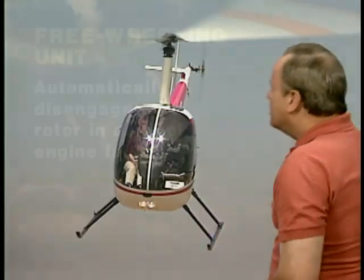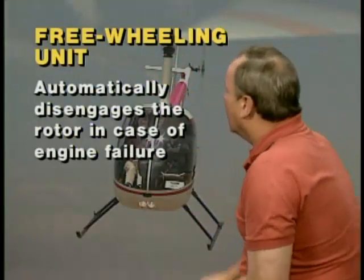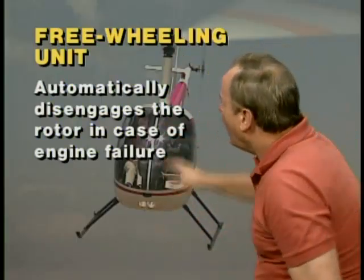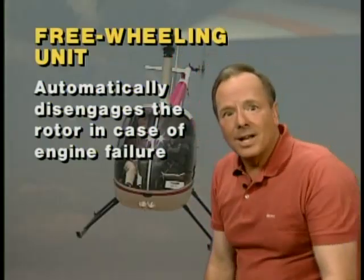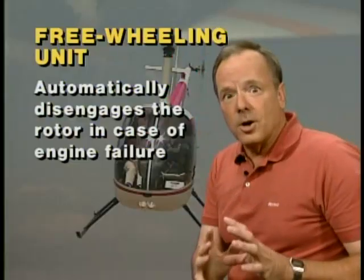And that solution is called the freewheeling unit or freewheeling clutch, and it automatically disengages the rotor in case of engine failure. Now, they're going to ask you on the test, why do you have a freewheeling unit? And one of the things they'll say is to reduce or relieve the starter load. No, that's not correct. You have another clutch for starting the engine.